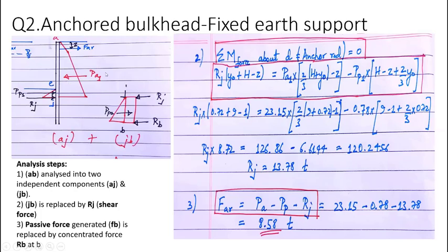Then what are the other forces? Now active pressure thrust is acting, passive force is there, so we can calculate this. We have earlier calculated PA1 acting at what distance. It's 2 by 3 of this height, where this height is H plus Y0 minus H. Then comes the passive force. So passive force acts at H plus Z minus 2 by 3 of Y0, that is, 2 by 3 of Y0 plus H minus Z.